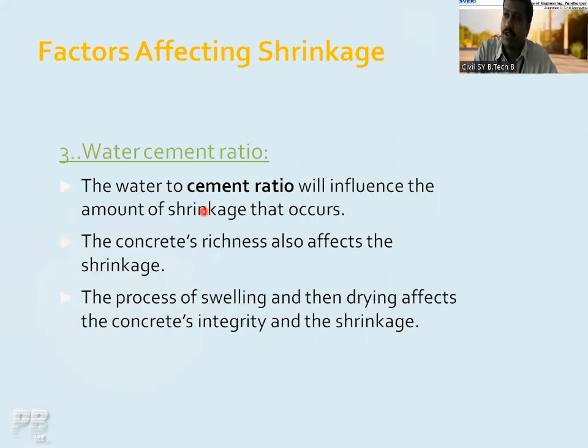It is very important for us to select the proper water to cement ratio. Because if you use a very low water cement ratio, shrinkage is prone to happen very early, at the earliest stage. But if you take the exact amount of water to cement ratio, then definitely it will reduce the intensity of the shrinkage as much as possible. So shrinkage will affect the concrete richness. Richness means its workability, or the ease with which we can place it.